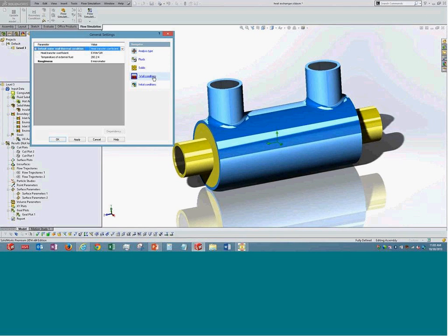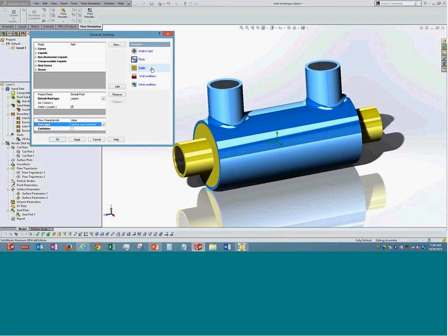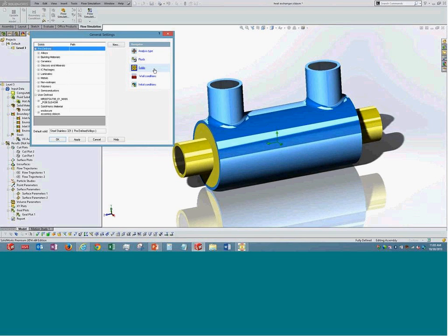Second, now that we have multiple fluids, we created the details over here. There is something called a default fluid. It is here. This has been selected as the default fluid and it is water or liquid. Now this fluid is assumed to be present in the entire system. However, there is one more closed domain inside this system which is to have air inside it.